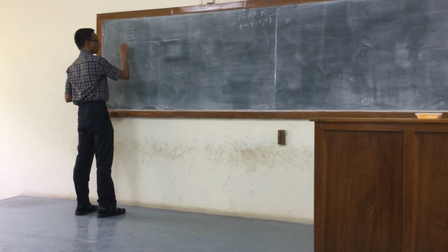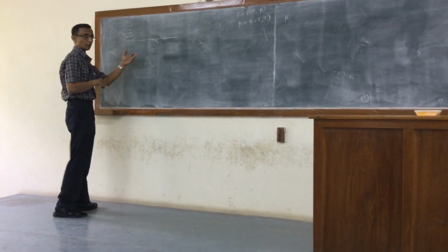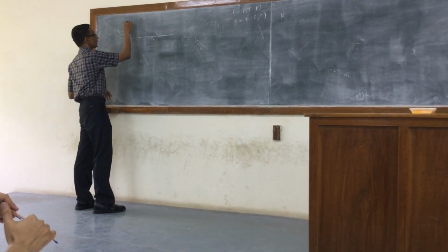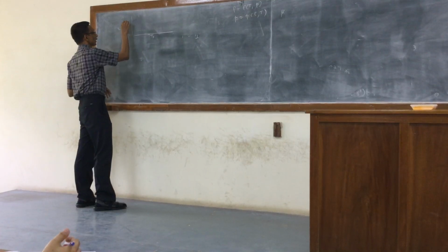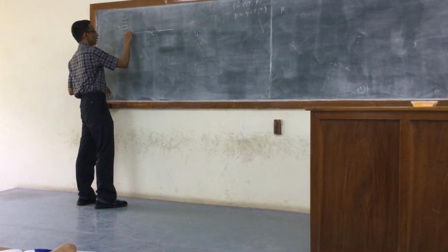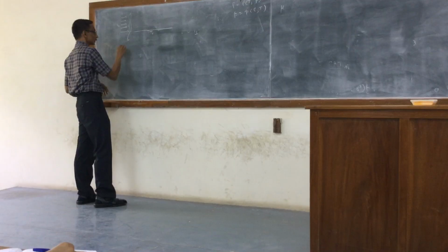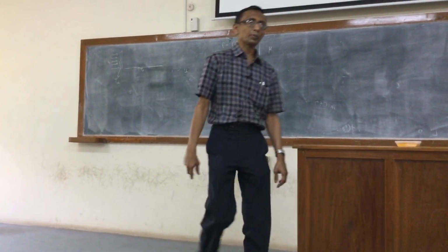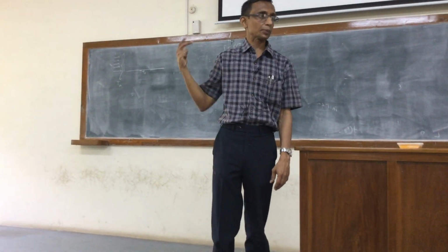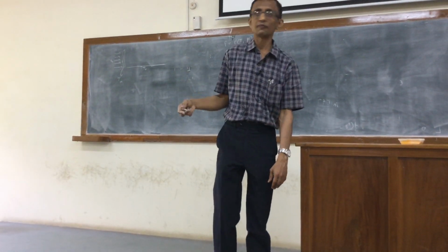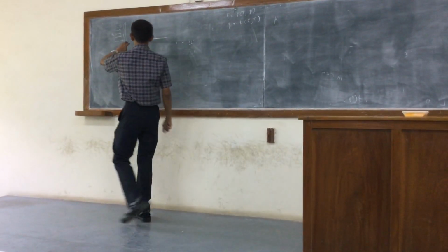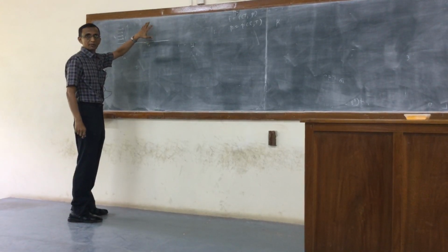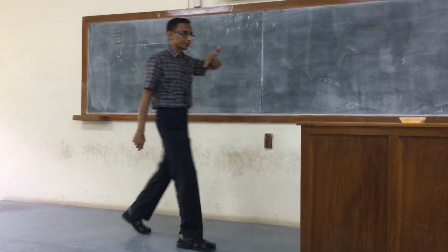On top of the flow, which we have already considered here, we consider T0, and then we consider the no slip boundary condition at the wall. Here the condition is T equal to T0, and the temperature of the entering fluid is taken to be T infinity. It enters at a certain uniform temperature, and then what happens when it passes over the plate? On top of the hydrodynamic boundary layer, we also have a thermal boundary layer, and we see how that is defined.